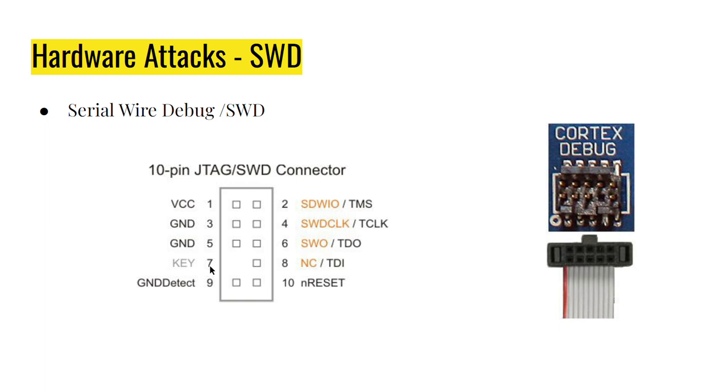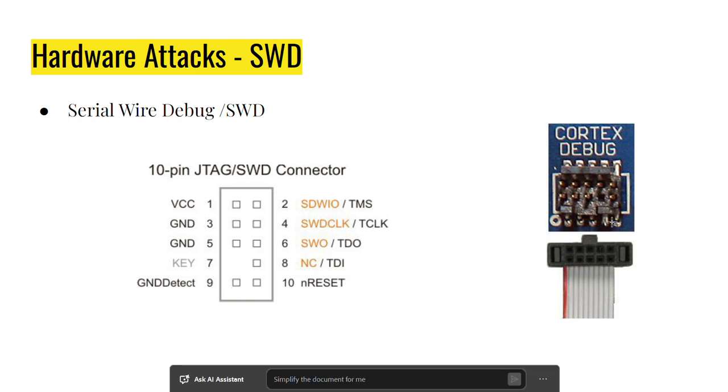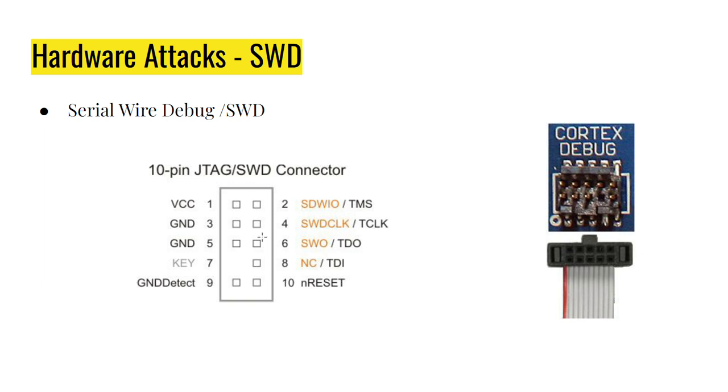And there's another protocol called SWD, which stands for serial wire debug. Serial wire debug is in most cases used in most of the STM32 based microcontrollers, but that depends. And these are the pinouts of it. It includes 10 pins.